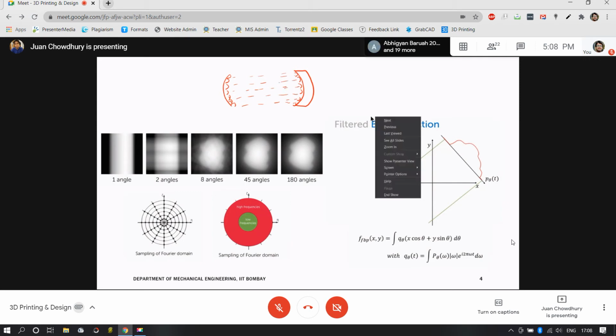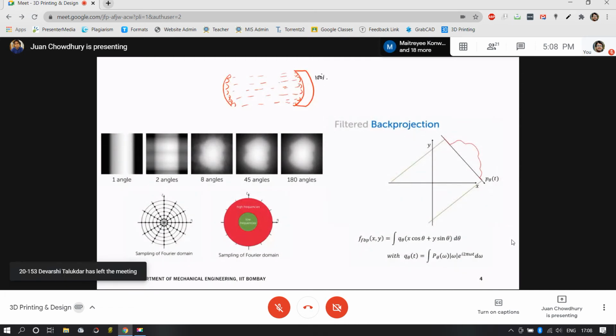Suppose now I try to detect what intensity is arriving at the detectors. I'll get 100% intensity, and maybe because of some interference from each beam, the intensities might vary slightly. So we calibrate the amplitude signal of each emitter. This part is called calibration, so that each detector now has 100% of intensity.